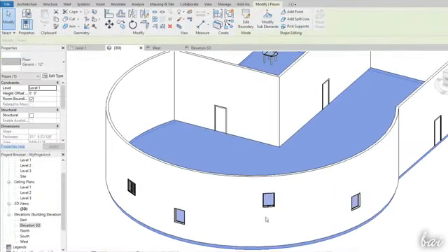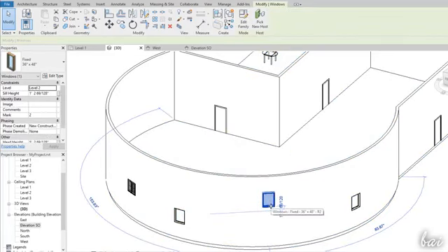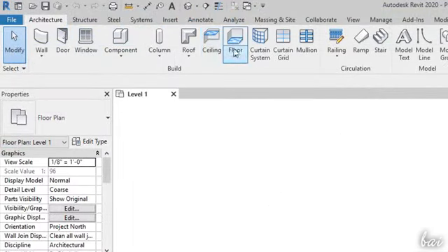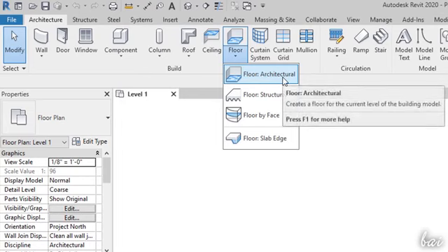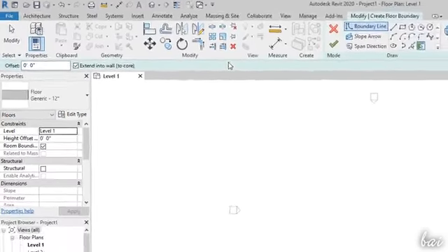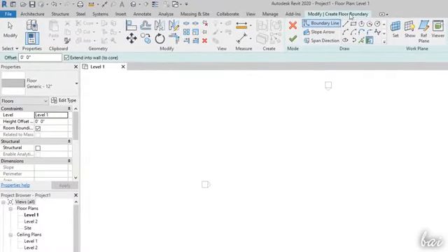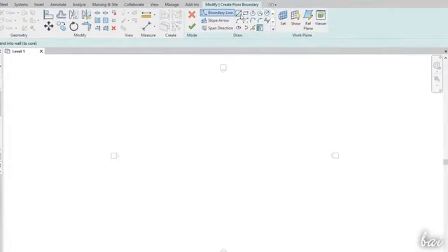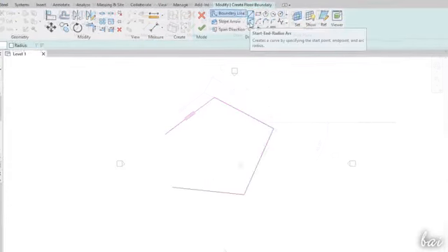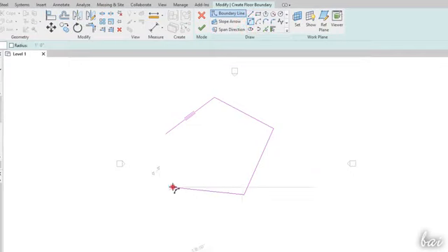Any building is usually made from the bottom to the top, designing first a basic floor by using the Floor tool. When any tool gets enabled, several drawing tools appear under the green Modify tab in order to define the object shape. Inside the Draw section, enable Line, Arc, or Spline to draw each straight or curved side of the floor.